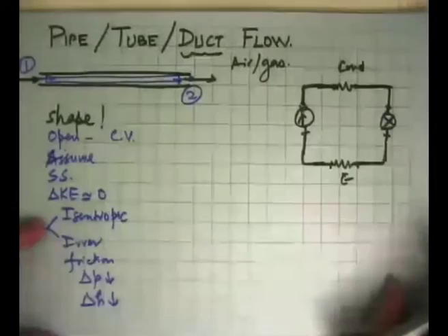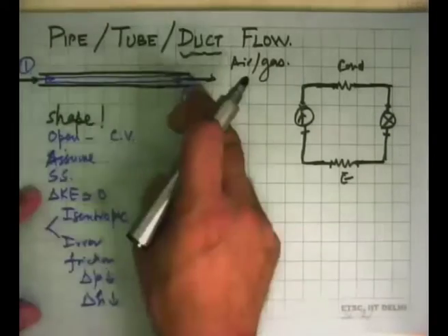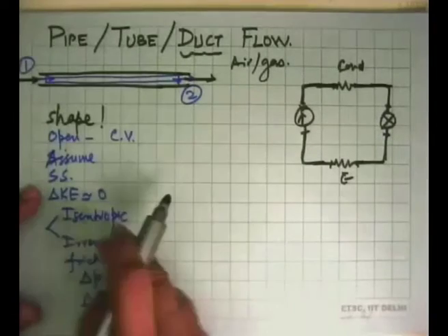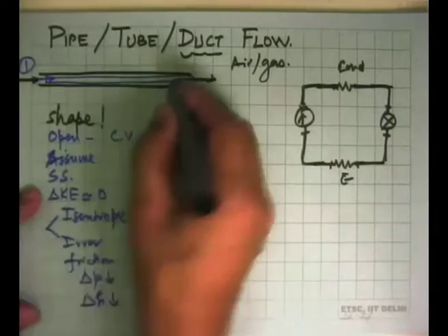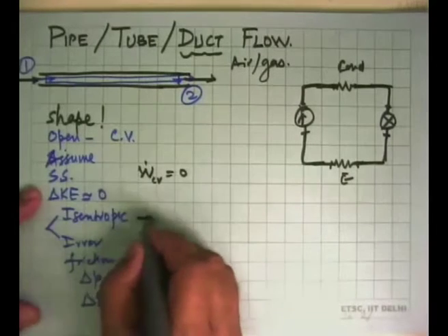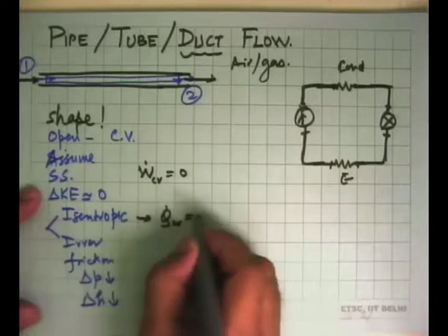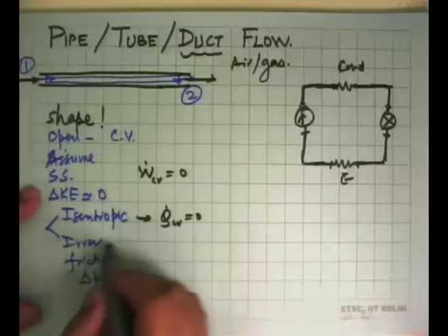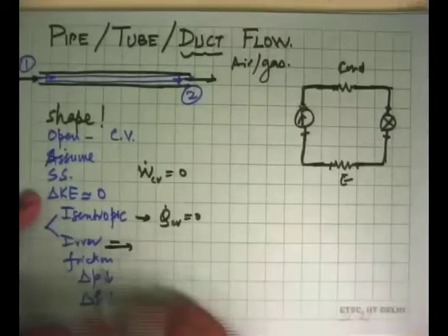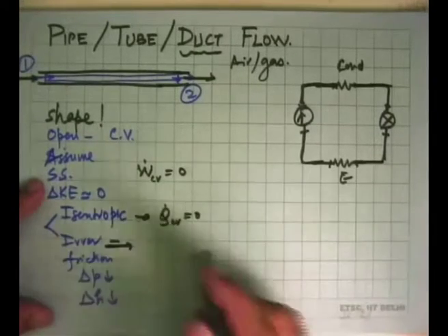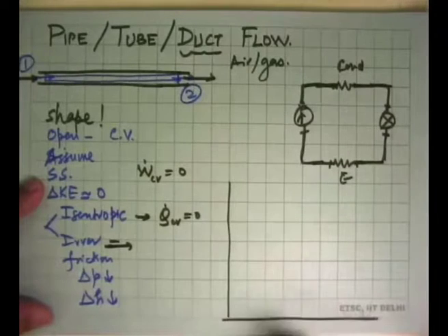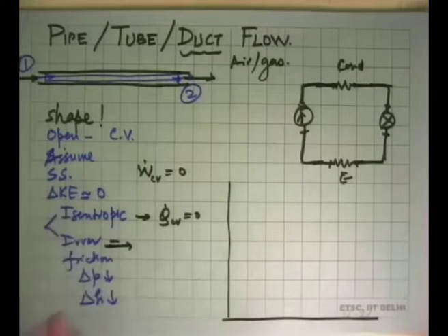But thermodynamics tells us that under these assumptions, this is what will happen in a pipe, and if we assume that this is isentropic, there is no work transfer in this, so W dot CV equal to 0. In the ideal case, Q dot CV is also 0, but even if this is 0, internal irreversibility, if there, could cause a drop in pressure. So what we do in treating pipes in a thermodynamic system is that